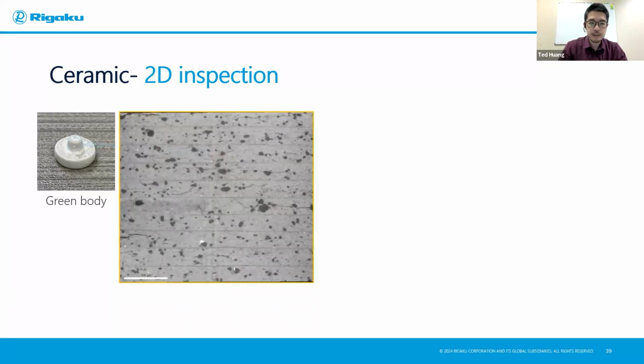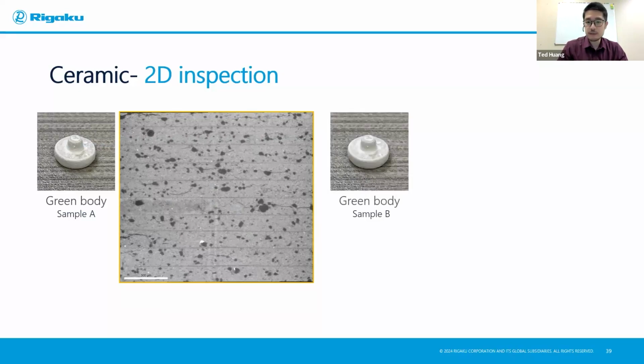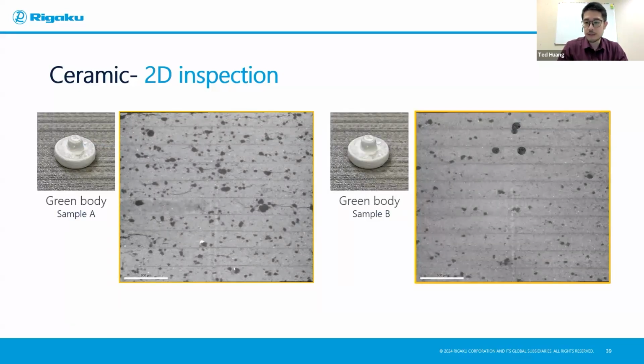And what we're seeing here on the left is this. You can see clearly different layers of the sheet laminated together and some of the secondary phases that are inside. And just for a comparison, this is one of the samples, sample A, with a certain composition. For another sample, that's sample B on the right side. You can see clearly the difference between them in terms of how the second phase is distributed and the existence of some cracks in one and a lack thereof in the other.